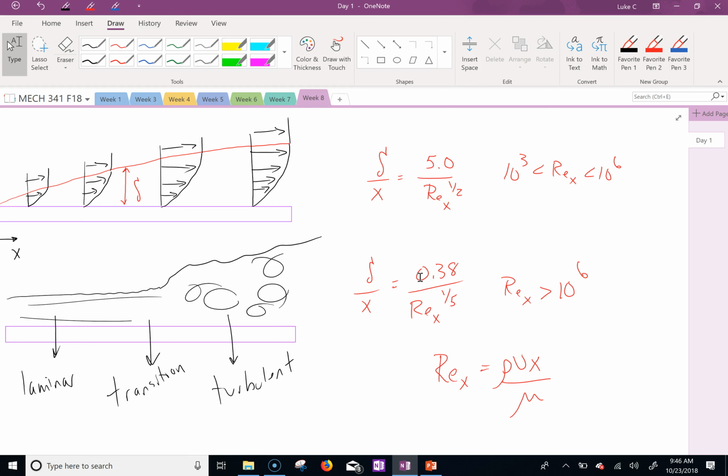Yeah, we get a wake region because, yes, the flow sticks to my surface, but you can't make it bend back down because of its inertia. Same with you running down the hall trying to make a curve. It just doesn't want to bend, and therefore we get that wake region. For laminar flow, the wake region is thicker. But for turbulent flow, it's smaller because you have more circulations back here that help grab some of the flow and help it shrink down. That's again why the golf ball with dimples creates turbulent flow, and you get these vortices, circulations, that help reduce the wake region.